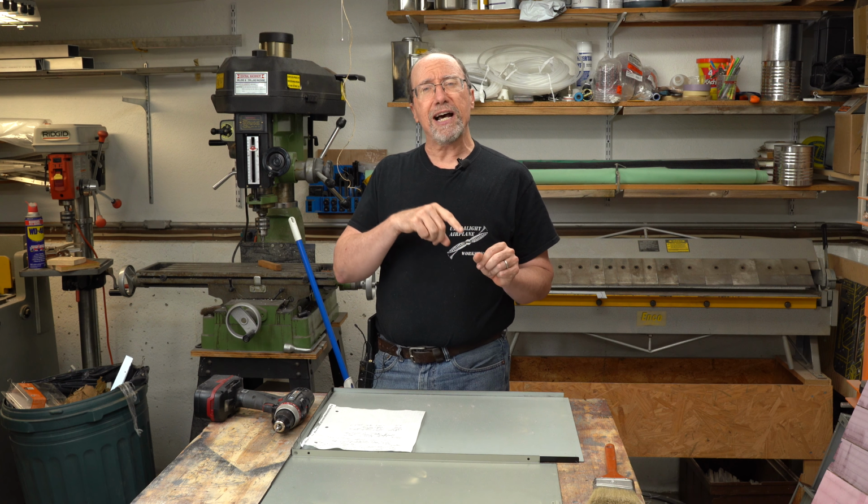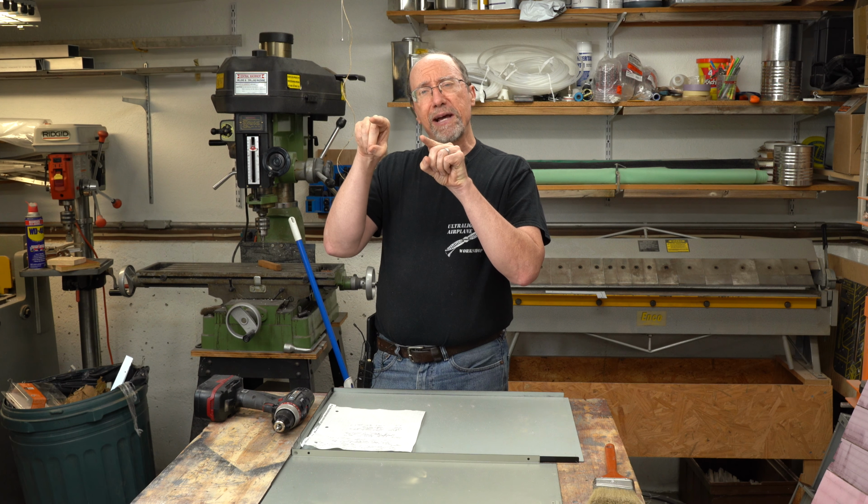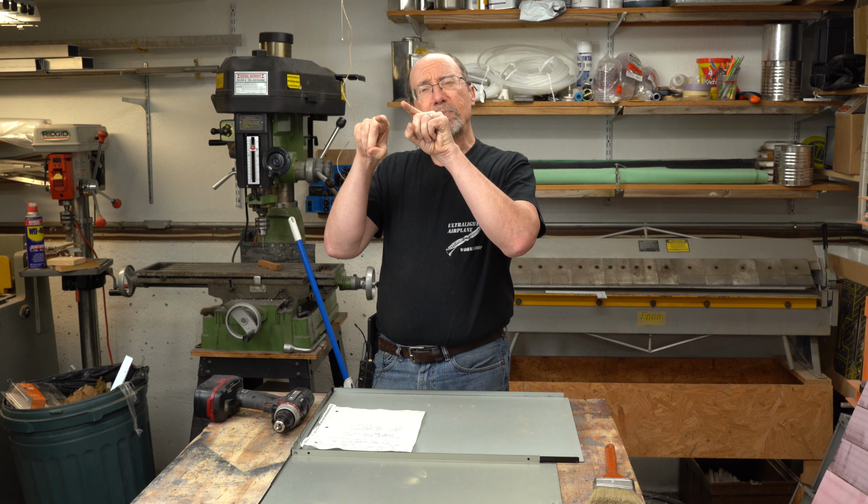So it's always going to report a higher coefficient of lift near the stall condition than you'll have in reality. Now you can trust it in the low single digit angles of attack. It'll be pretty good there. And it'll be pretty good up until you start getting that round off on the coefficient of lift as you're approaching stall. So the closer and closer you get to that maximum coefficient of lift, the farther apart it'll get. And once you get past that maximum, the vortex lattice method really isn't reliable at all. So that's why I normalized those lift distributions for 105 pounds of lift.